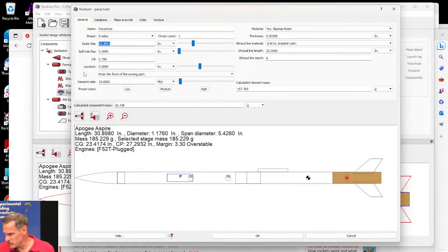from Michael Davis. And he says, I have a couple questions about loading motors into RockSim for you today. I was trying to load some Aerotech motors into RockSim. Files were sourced from ThrustCurve, but they wouldn't show up in the choose a motor window. Discovered the files that wouldn't load had an extension of .eng.